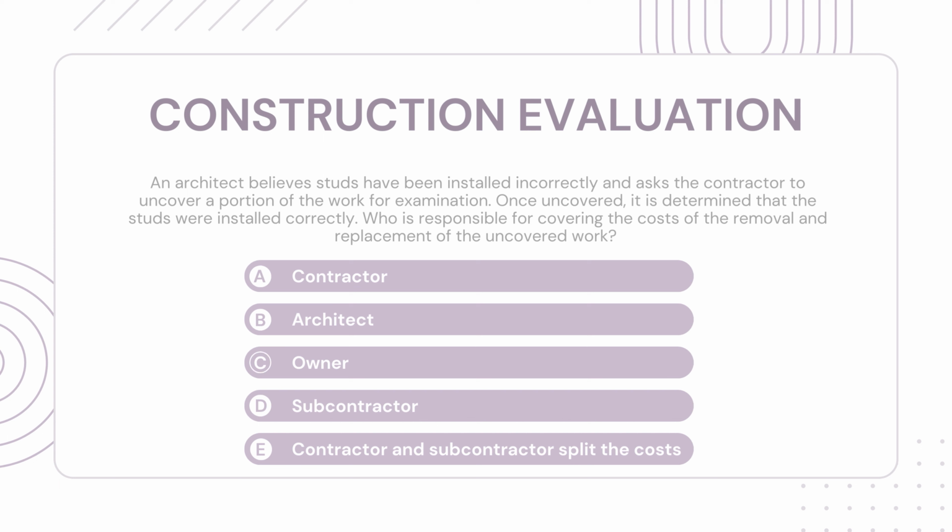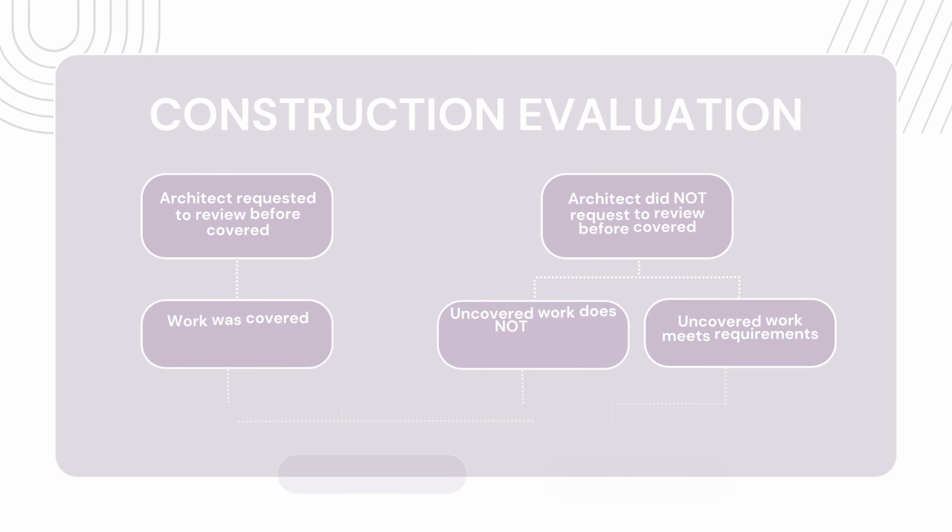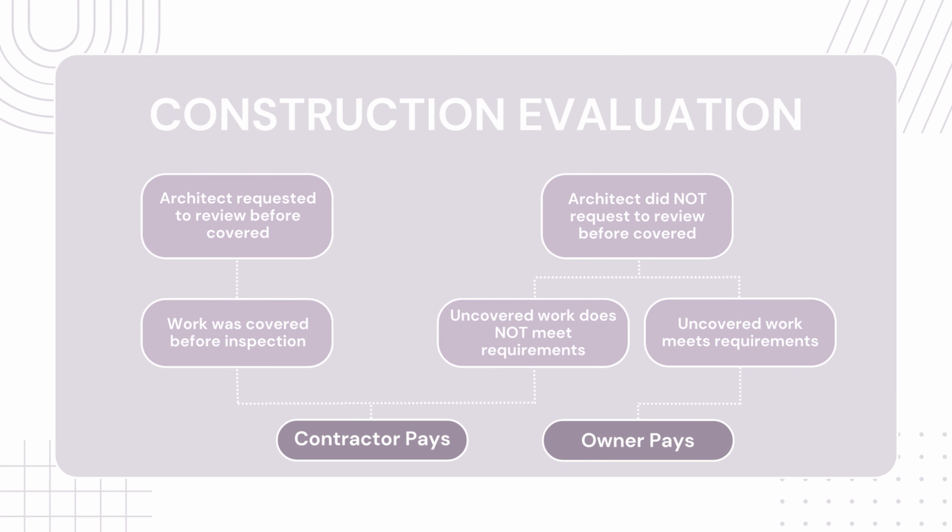And the answer is the owner. Since the architect did not specifically ask to inspect this work prior to it being covered and it has been found to conform to the contract documents, the owner is responsible for payment via a change order. If the work did not meet the requirements of the contract documents, the cost would be the responsibility of the contractor.